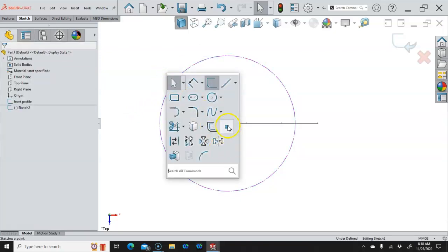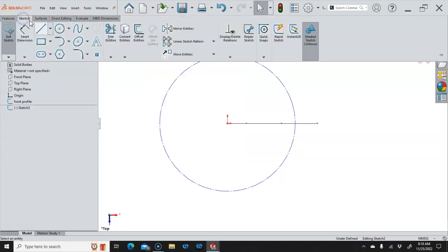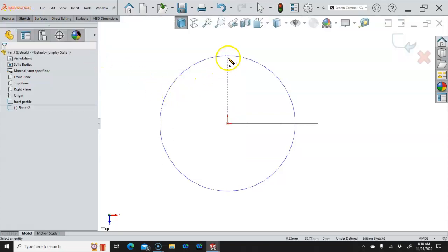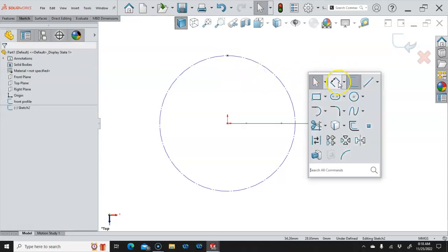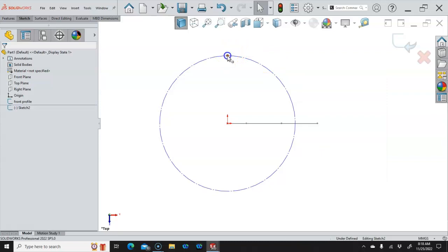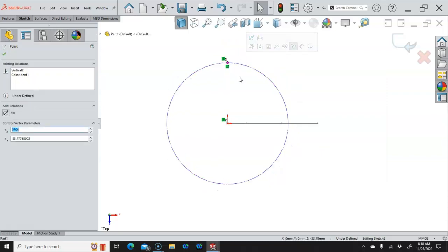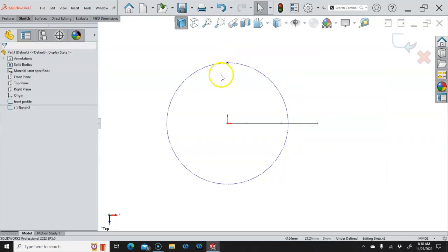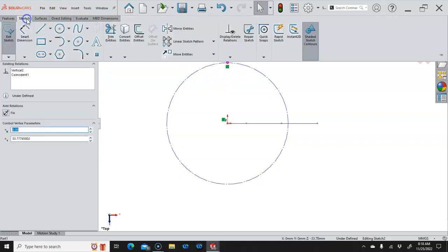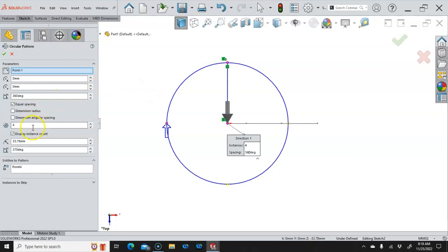I've added the point to my S key, but if you haven't done that yet, then we'll go up to sketch and position. The dimension of this would be the 75, but if I want to use the base circle and have the circular pattern generate that radial dimension, I'll leave the dimension off for now.